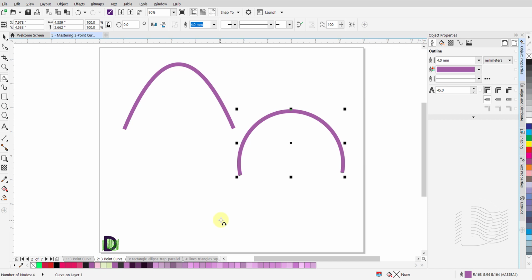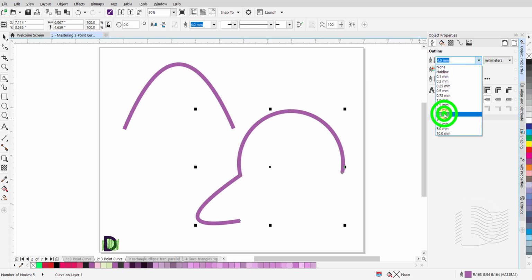To add a segment to a previously drawn straight or curved line segment, utilize the bent arrow to add the extension. Hover your mouse over the point where you wish to start the extension until you see the bent arrow. Click and hold the left mouse button. Move the mouse to the intended end point of this segment. Release the left mouse button and move the mouse to form the curve. Left-click once.